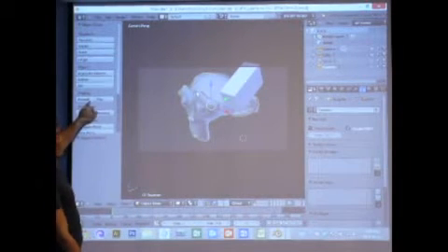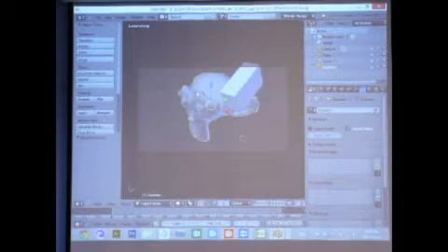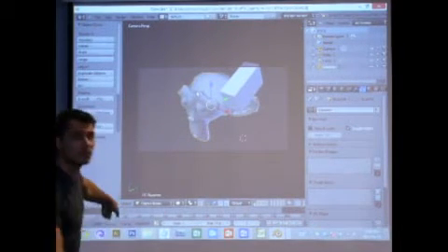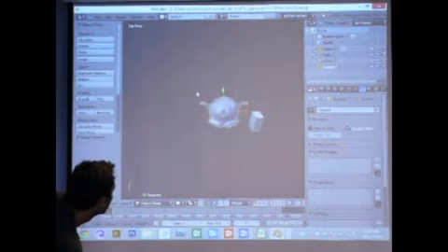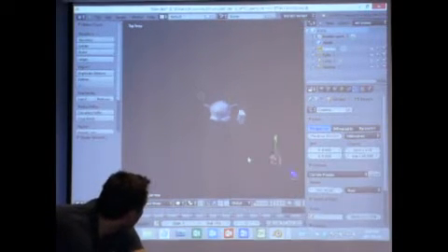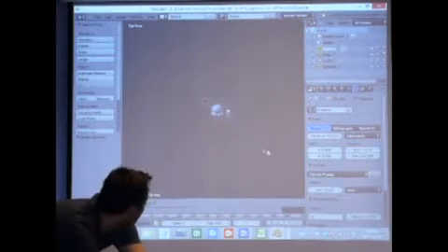Right, smooth. Yes. How can I change the dimension of the camera to scale? Because otherwise some pieces are rendered outside of my window. Yeah, so usually in that case you'd want to switch your view to the top. And you locate your camera, so camera here is right here. You zoom out quite a bit, you grab your camera and just move it farther away.